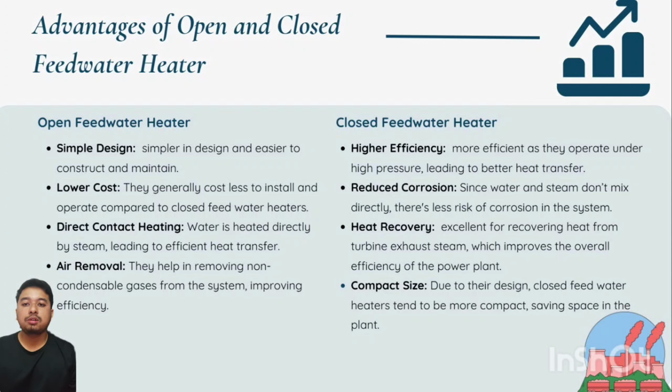Second, reduced corrosion. Since water and steam do not come into direct contact in closed-feed water heaters, there is less risk of corrosion. This is because the feed water is contained within tubes and the steam flows around these tubes, preventing any direct mixing. Third, heat recovery. Closed-feed water heaters are excellent at recovering heat from turbine exhaust steam. By capturing and utilizing this heat, the overall efficiency of the power plant is improved, leading to energy savings.